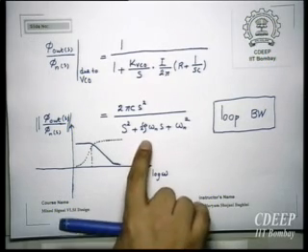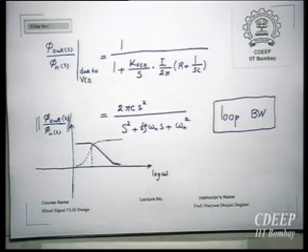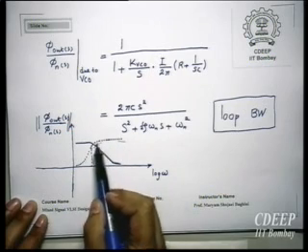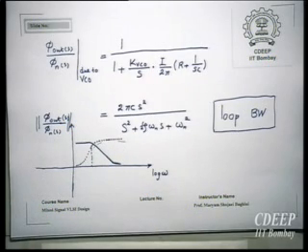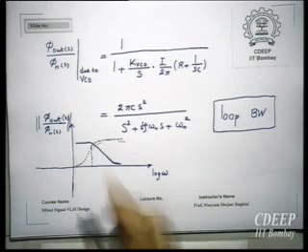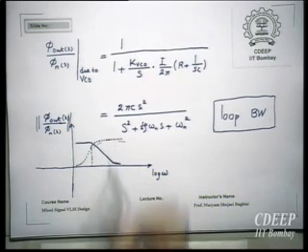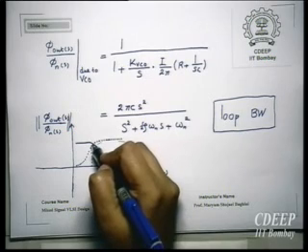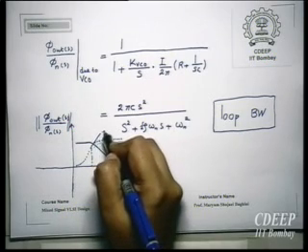If you look here, poles will be imaginary, right? What will be the root locus of this? I will just plot it. Because I am showing this high pass filter in this way. But actually this high pass filter won't be as simple as this. It won't be flat here. It will even show some peaking, right? Suppose your zeta is less than 1. The whole low pass filter will show peaking. And then if it shows peaking, then actually you will have something like this.